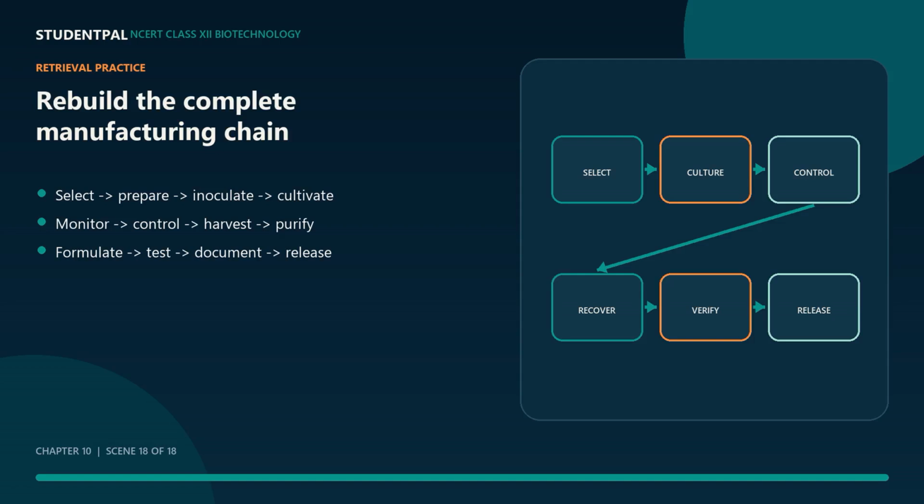Bioprocessing uses cells, components, or enzymes for controlled conversion. Biomanufacturing makes the process reproducible at production scale. Product timing can follow growth or specific later physiological conditions. A bioreactor integrates mixing, aeration, heat transfer, sterility, sensing, and sampling. Oxygen transfer must meet demand without unacceptable shear, foam, or heat. Batch begins with a fixed charge. Fed batch adds selected nutrients and continuous operation balances feed and output.